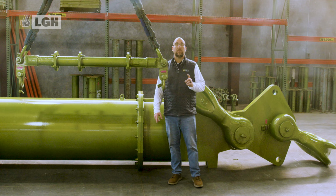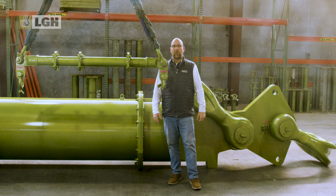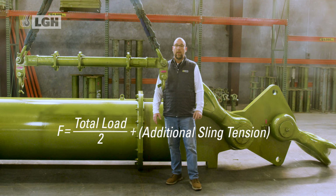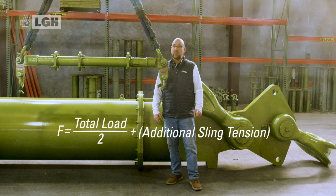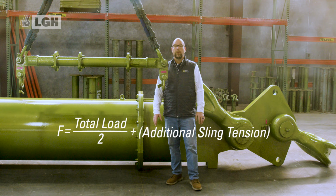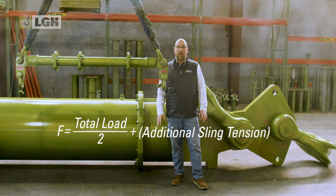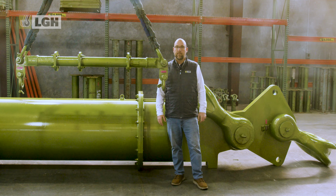To calculate the correct load distribution, let's use the formula. F equals total load divided by 2, plus the additional sling tension. Here is what these variables mean. F equals the force experienced by each sling and connection point. Total load equals the weight of the object being lifted. 2 equals the number of slings supporting the spreader beam. We're assuming a 2-leg setup here. Additional sling tension equals the increased force due to sling angle effects.